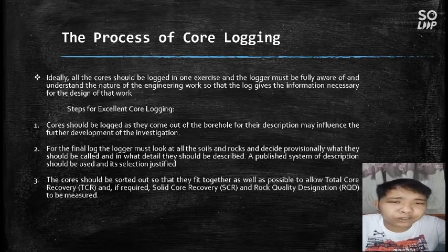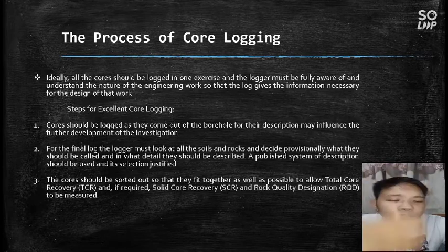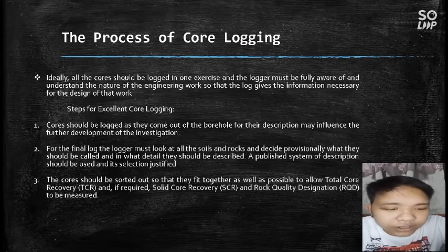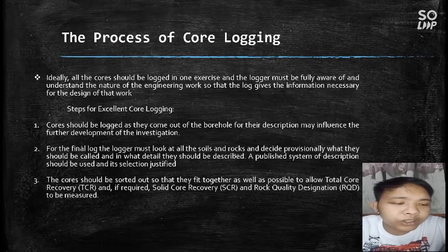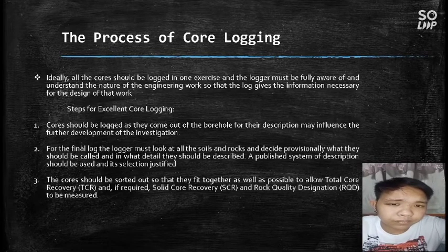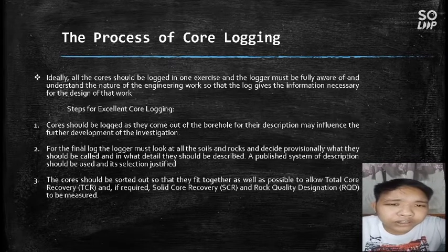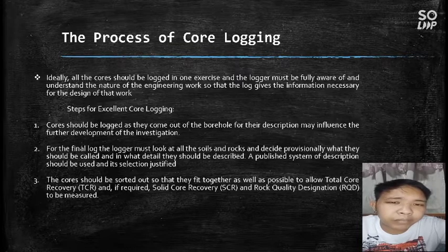So, I will show you the steps of core logging. First is that the cores should be logged as they come out of the borehole, for their description may influence the further development of the investigation. Right after being excavated from the borehole, the cores should be investigated at that moment, because they may change as they are being stored.